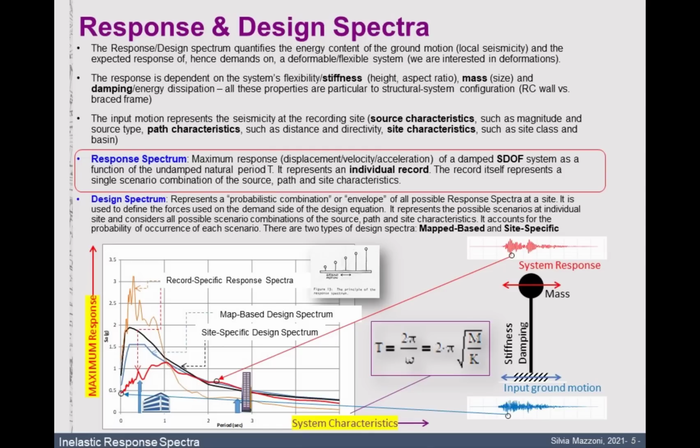We jump right away to response spectra. And again, this is a nice, big, long definition in the slide. The point of the response spectrum is to give you an idea, not just of the amplitude of your earthquake, but also of the frequency content. Based on that, the frequency content is going to give you information about the response of your structure. So in one plot, you can identify right away everything about how your building is going to behave, and just in one simple figure.